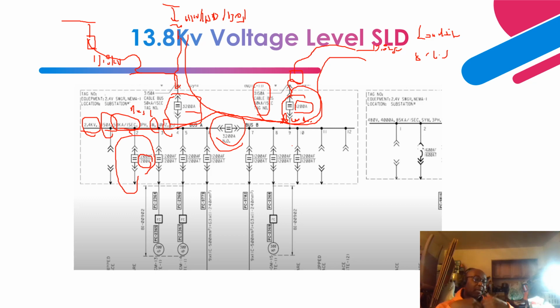Some of the breakers have trip logic schemes that help to set the protection schemes. The trip logics have a long time pickup, long time delay. They also call them solid state tripping pickups.